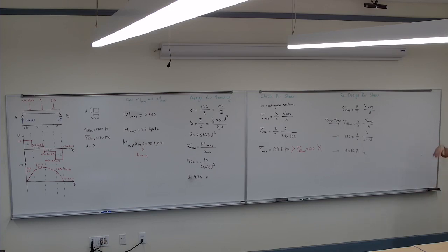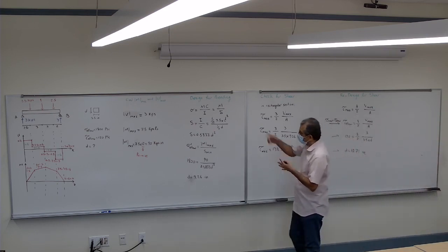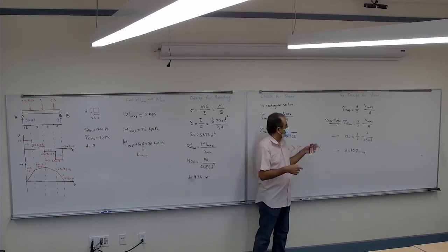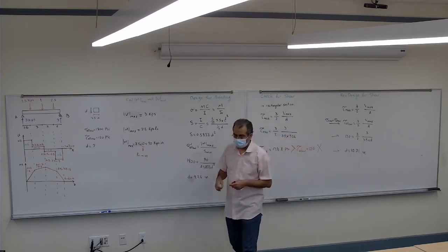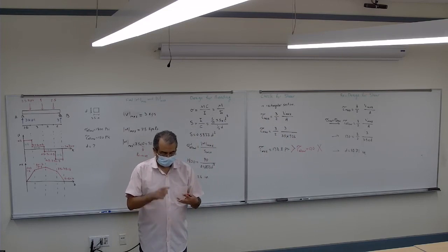Whatever type of force you have on that, axial, torsion, bending, and shear, these are one of these 4. You find the maximum for them, and then you start to design for one of them, and you recheck for every other case. And if it fails, redesign it, and again recheck it until you make sure it's not failing under any of these: axial load, torsion, bending, and shear.